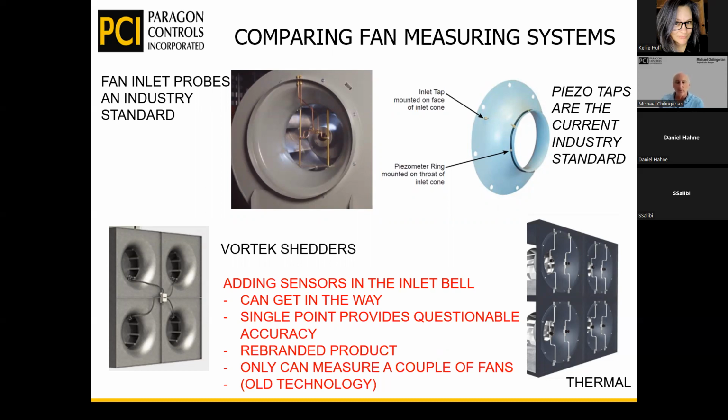It's something that works well, but we have something else today, which is the piezo taps or piezo rings, which Pace brought to the world a number of years ago. It's a really much more elegant way of doing it, because we really don't have anything in the inlet bell anymore. It basically works with Bernoulli's principle, and we have a differential pressure, and we have a venturi, and it's a very nice system. It's very elegant for doing airflow measurement at a fan, and I think it's just terrific.